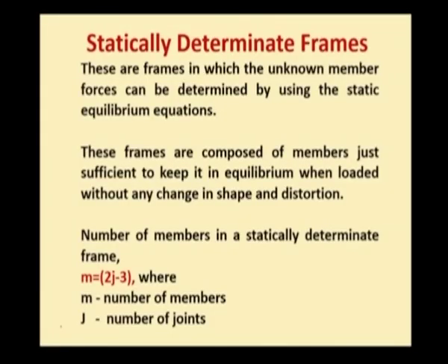A statically determinate frame is one in which the unknown member forces are determined by using the static equilibrium equations. Basically, there are 3 static equilibrium equations which are as follows: algebraic sum of all vertical forces equal to 0, that is sigma V equal to 0; algebraic sum of all horizontal forces equal to 0, that is sigma H equal to 0; and the third equation would be algebraic sum of moments of all forces about a point in the system equal to 0, that is sigma M equal to 0.